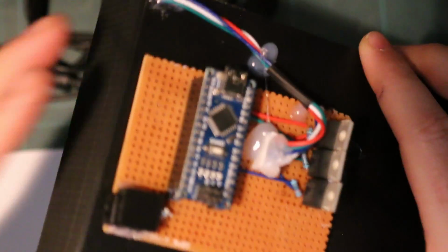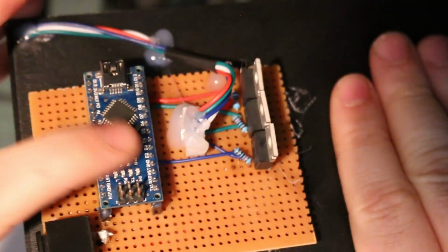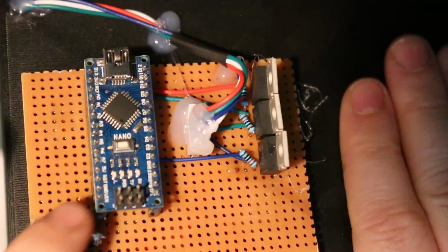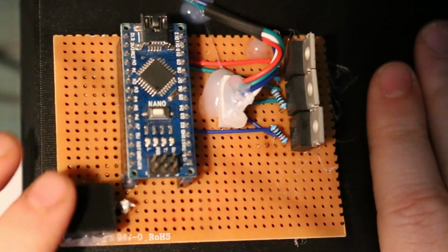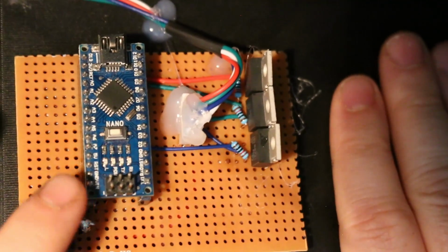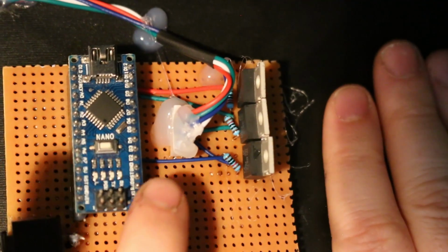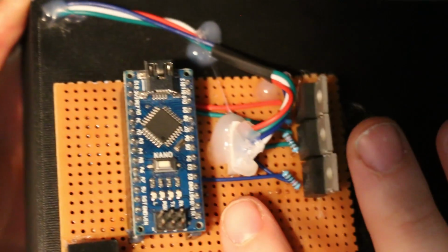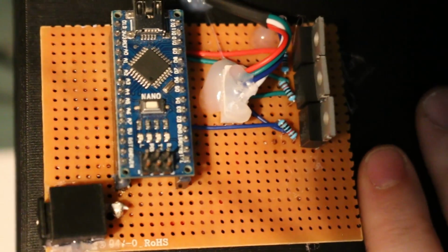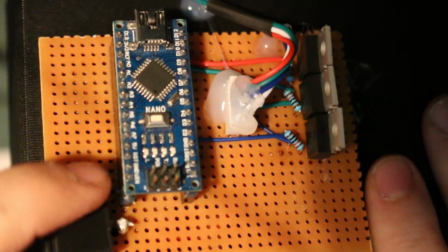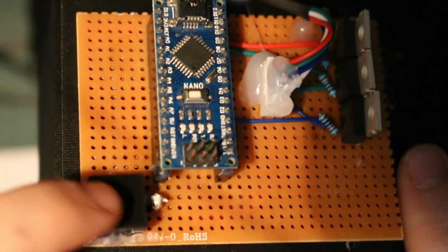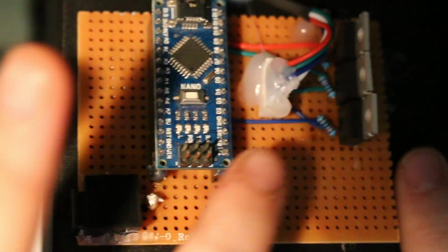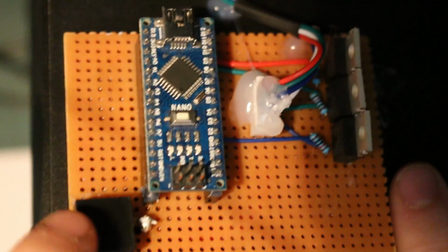So the mistake I made initially, and how I fried one of these mini Arduinos, was I had the power connected directly to these MOSFETs and to this, as was intended. However, there's multiple ground pins on this Arduino, so I connected the transistors directly to the ground of this, which normally isn't a problem. However, I then connected the ground of this to here, so effectively these transistors were connected to this pin, having to go through the Arduino on the ground.